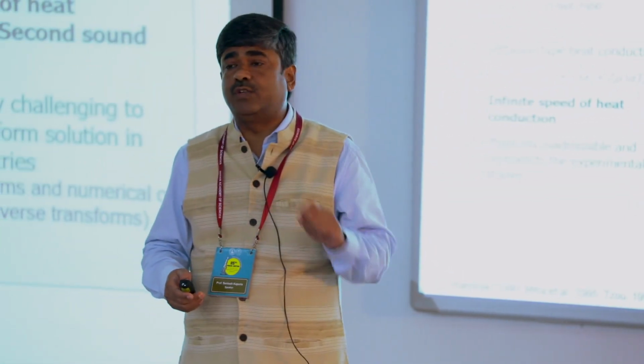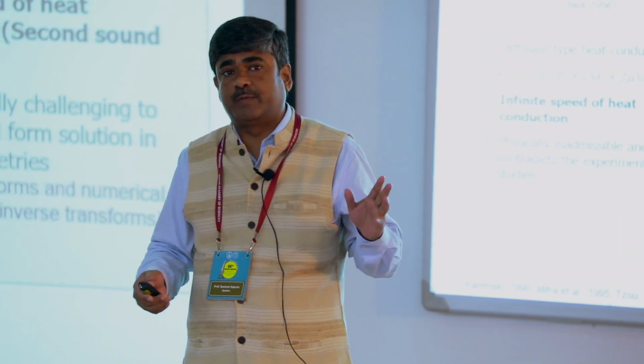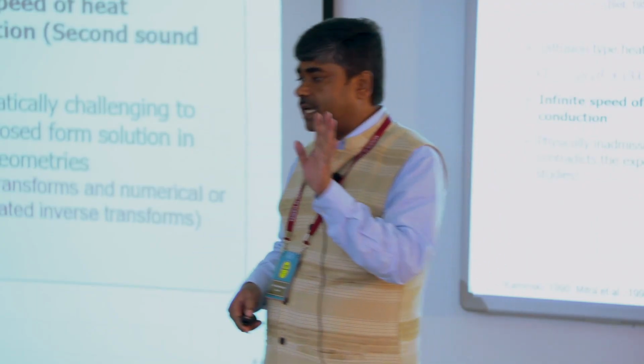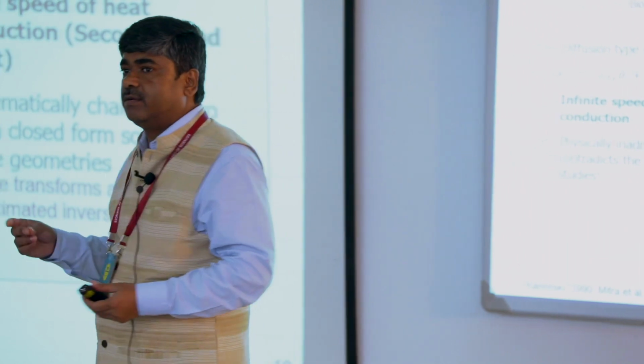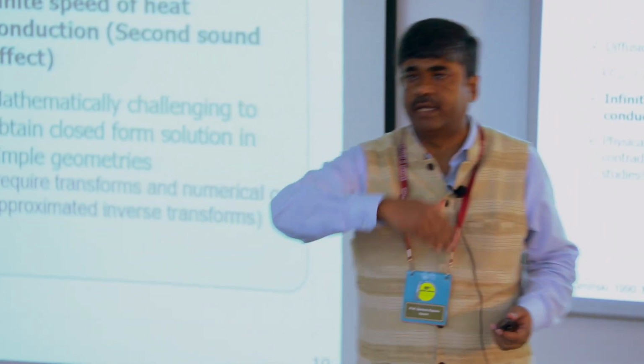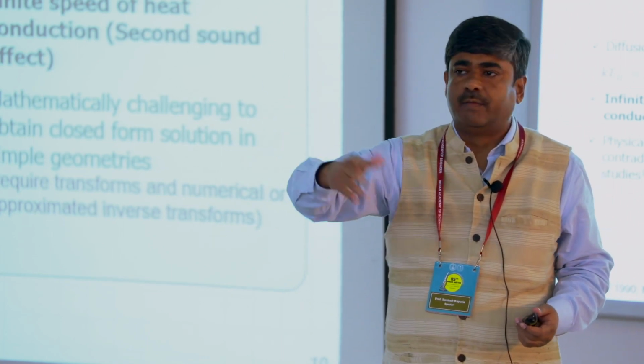Without going into the merit or demerit of this, because I am not a specialist on that, the problem is that the classical coupled thermoelasticity which Biot gave gives infinite speed of heat conduction. Essentially, as per that analysis, in no time the heat can reach from one end to another end, but it never happens.